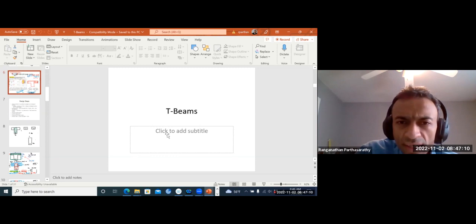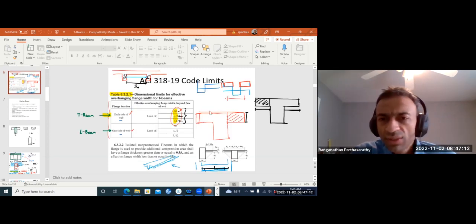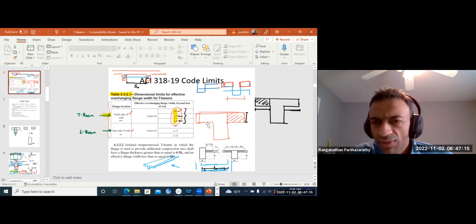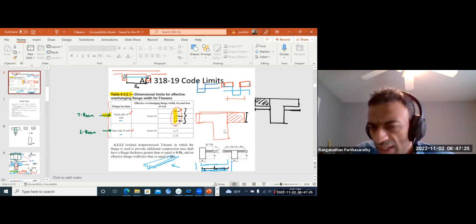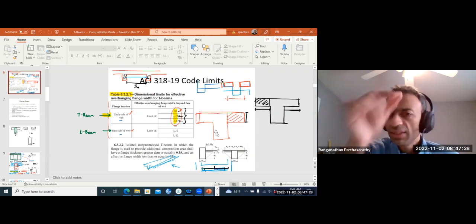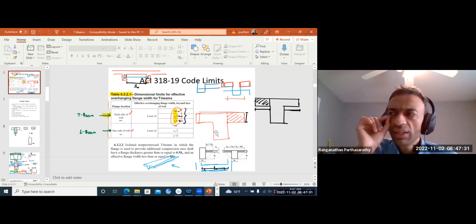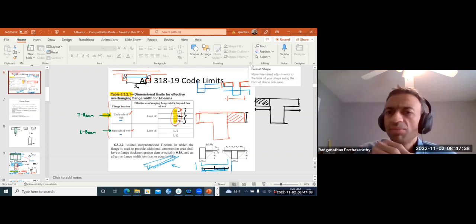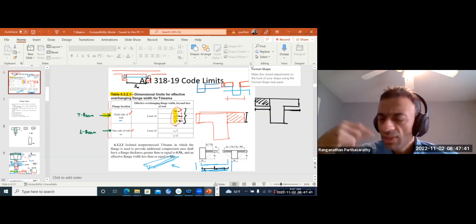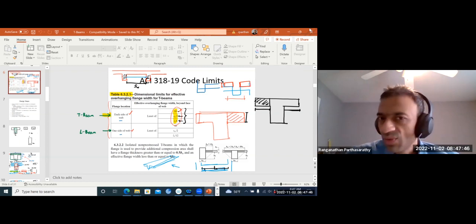So that criterion, I think you all may remember. You can find some effective width of this T-beam because of the non-uniform distribution in stress across the width and so on. So when we have the beam which is inside the column strip in our bending direction, then within that column strip, whatever moment we are assigning, some part of it will be carried by the beam.